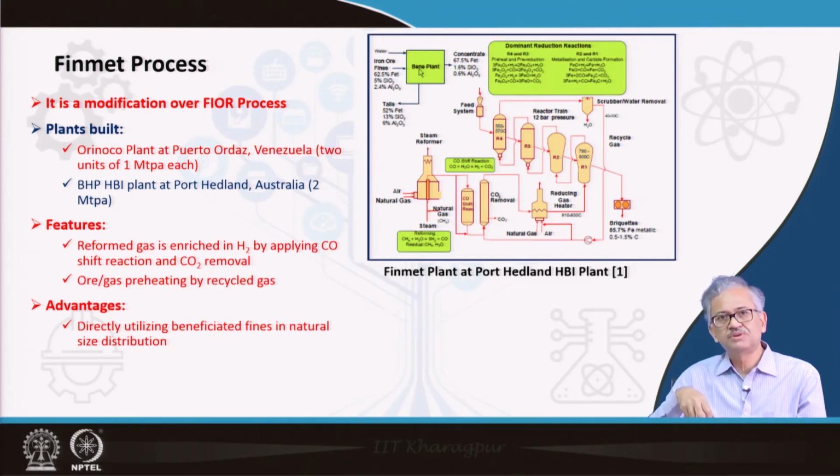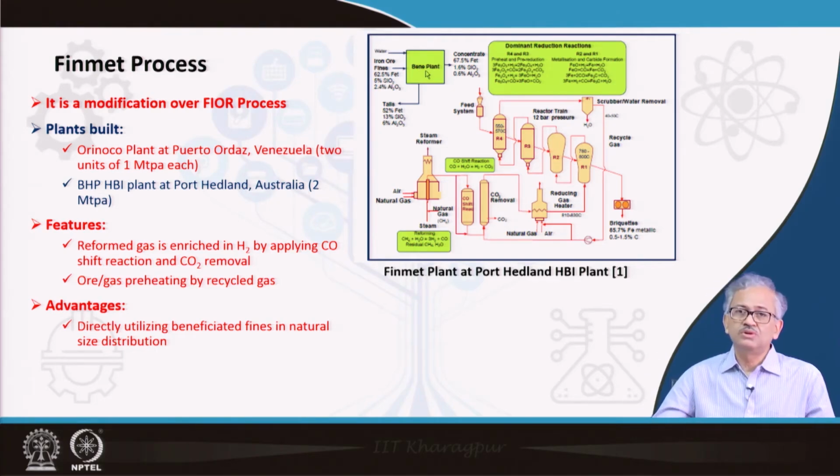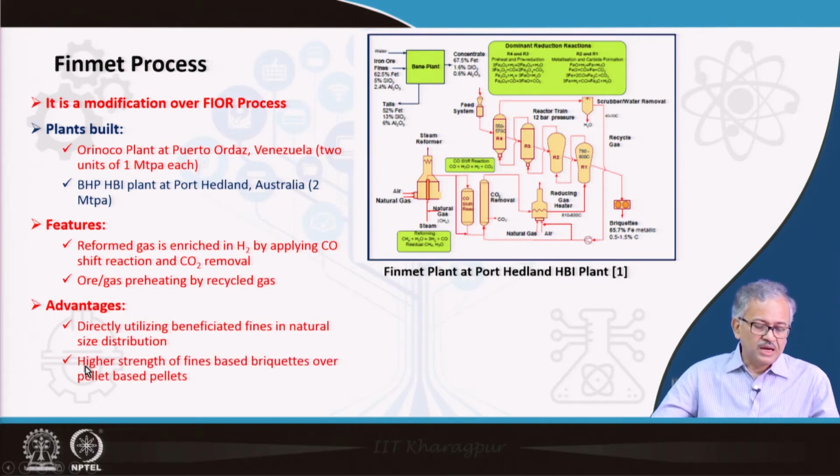And the advantages are directly utilizing the beneficiated fines in natural size distribution. Whatever the original size, after beneficiation you just charge that feed material without any grinding, without involving any energy intensive process.